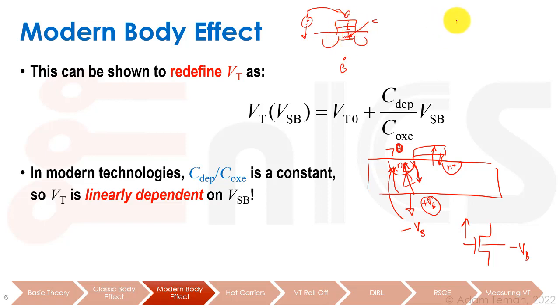So basically we have this capacitor, which is CG to channel. This is G, this is the channel, which we can't actually touch, but we can look at it. We want any voltage that we put on here, plus VG, to be applied to our channel. The problem is that there are other capacitors over here. One of them is CGB. Another would be our capacitance to the drain and our capacitance to the source, CGS and CGD.